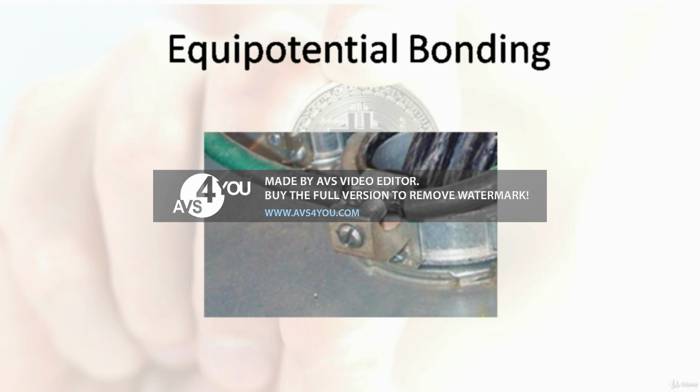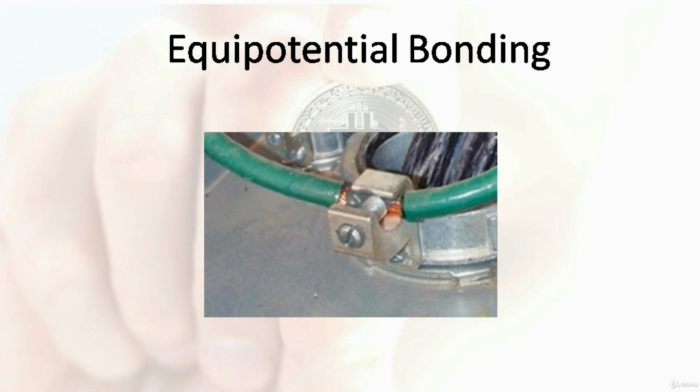If you're concerned with electrical safety, meaning that during an electrical fault, it might cause potential injuries while you were tinkering with the equipment, which, just so you know, is very unlikely given the amount of current and voltage level that it will be at your site. But nevertheless, you can still use electrically rated PPE such as electrically rated boots and gloves to touch the equipment if you have a concern of electrical fault and electrical safety.